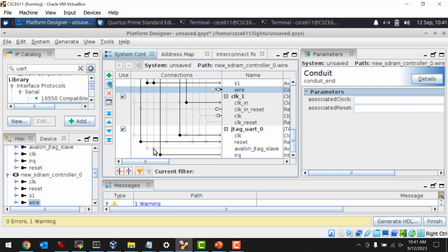Like the computers here actually have a power on self-test BIOS section, which it actually grabs, which is a ROM on the motherboard, right? I don't know if you guys have ever built a computer, but if you boot up a computer with no hard drive in it, no operating system, you'll still see it printing stuff when it turns on, because it's fetching instructions from a ROM that's on the motherboard before it branches to the operating system, which is on a drive, right? So you could have multiple instruction masters for that reason if you wanted to have like a bootstrap or bootloader section in there.